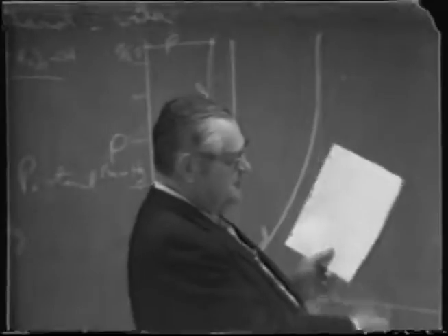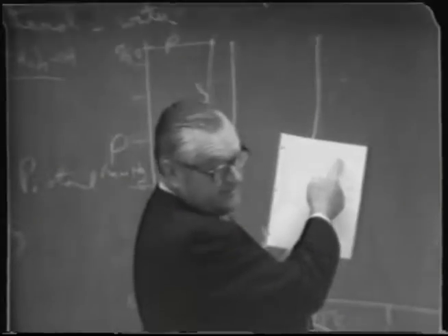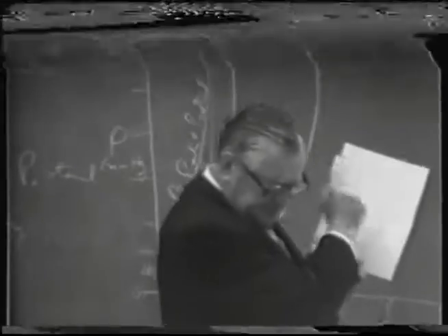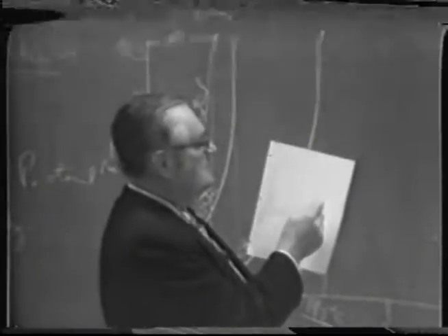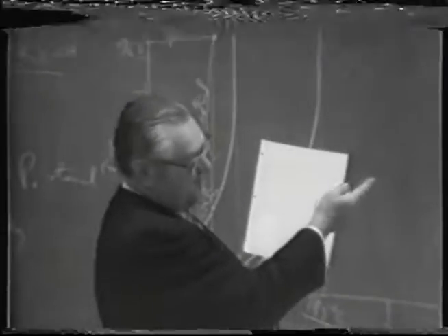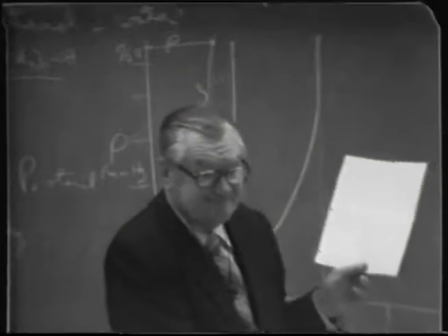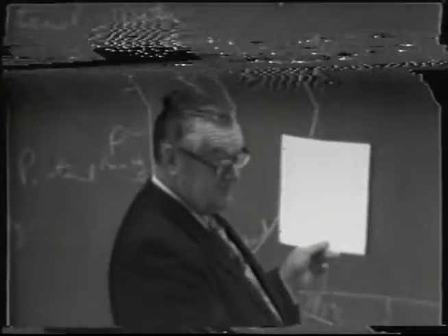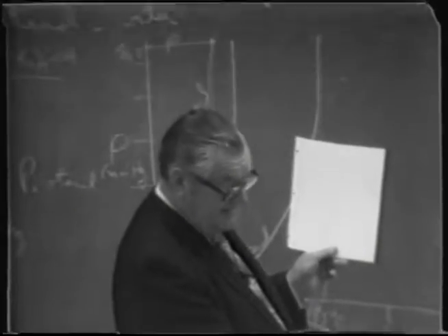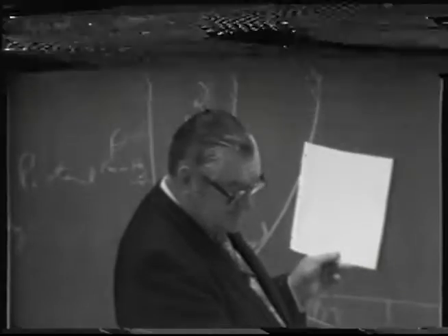And you can see it progresses from the first in the series. These are the systems of the primary alcohols with water. Perhaps I didn't say, the first one, methanol, forms no azeotrope. It forms a normal behavior system with water. But the next one, ethanol, forms an azeotrope at a fairly high percentage of the alcohol, 95%.